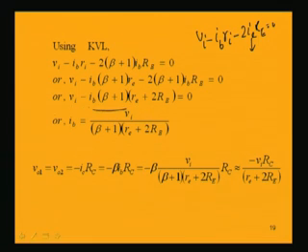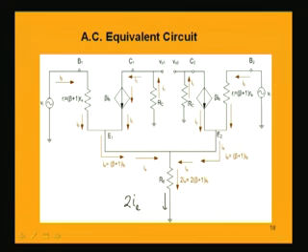So, now from this equation we can get what is Ib. The base current is given by Vi by (beta plus 1) into Re plus 2 capital RE. So, this is the base current. If this is the base current, we can find out the output voltage at both the terminals, V naught 1, which is equal to the voltage V naught 2, and that is equal to nothing but minus IC into RC in both the cases.